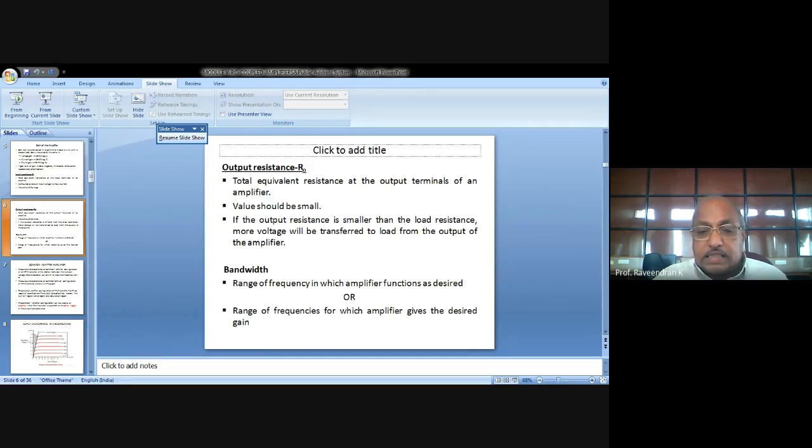I just gave the letter suffix here with a small letter because the other figure has the resistor RE with a small letter suffix. So RE stabilizes the operating point against the temperature variations. The operating point should always lie in the active region of operation for proper amplification.